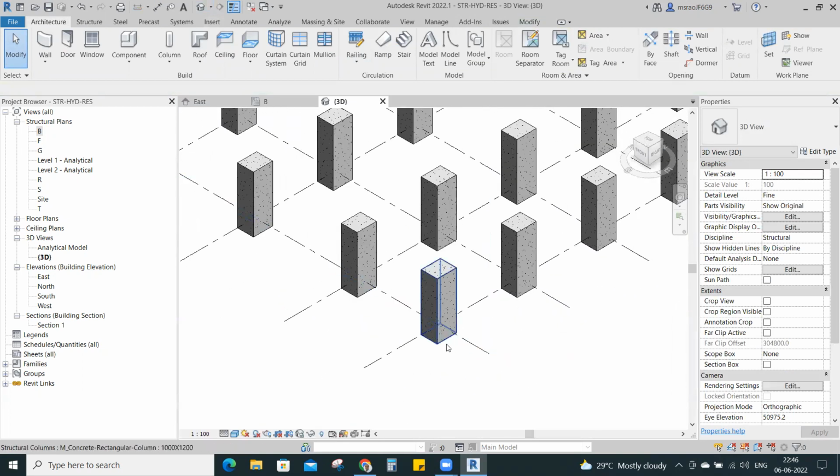Now I want to place a foundation for this column. Below the 500, yes, I want to place a foundation. When you place a foundation, always the foundation will go to the bottom of the column. You may ask one doubt: in real construction, first we put the foundation, and above the foundation we place the column. That is the process, correct? Here, we placed the column first, then we are placing the footing. A little bit reverse direction, because of utilization of the software properly.